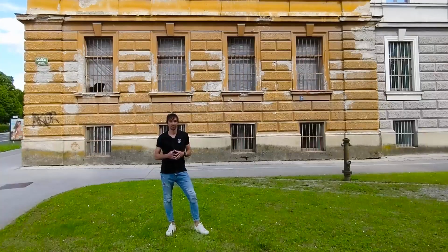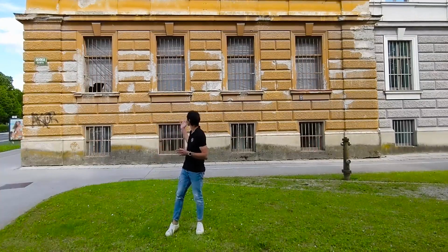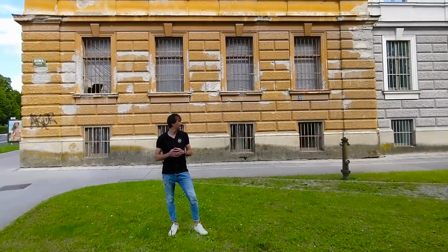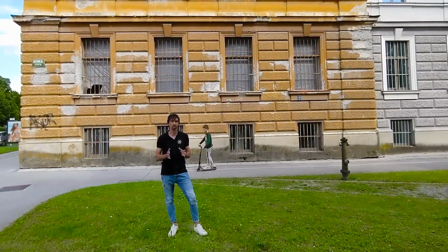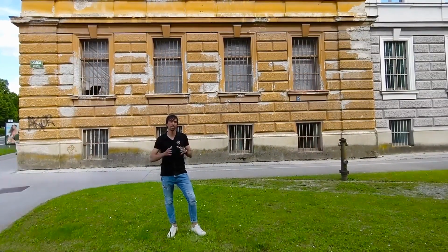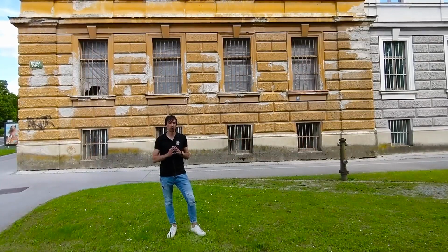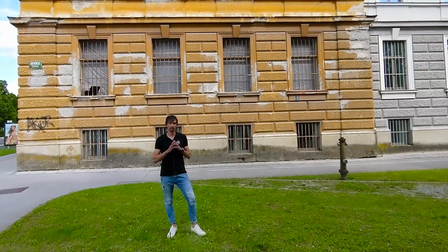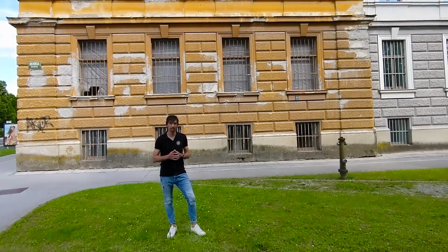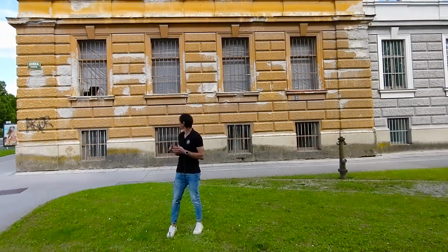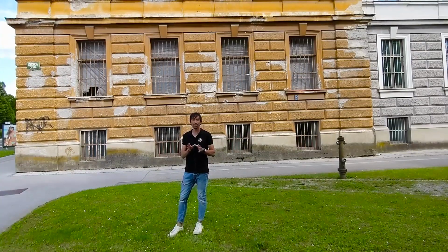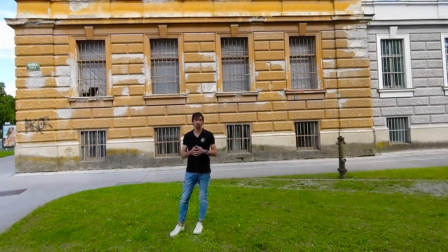Okay, behind us is a super nice old building, which is a cultural heritage building, and they will start restoration works. Before they do the restoration work, we would like to document the complete building with all the building facades in high detail. We would like to produce an orthophoto with a resolution of 1 millimeter and a textured 3D model with all the small details, which are super important, and to have them documented in 3D to do the restoration work properly.